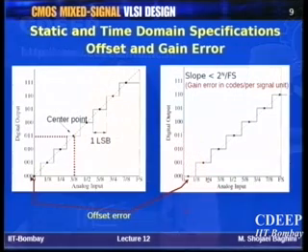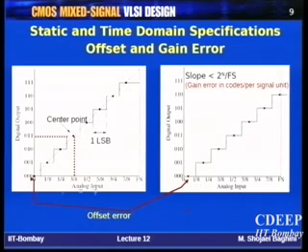The reason is that your reference values may not be exactly that reference value. So every reference value may have some small change. You expect your transition point to be exactly here, but now your reference has shifted to the left or right. Therefore, you will have some plus minus delta V shift of the center point everywhere. This creates some change in the location of these reference points.